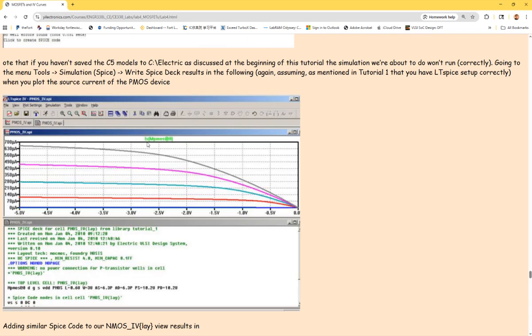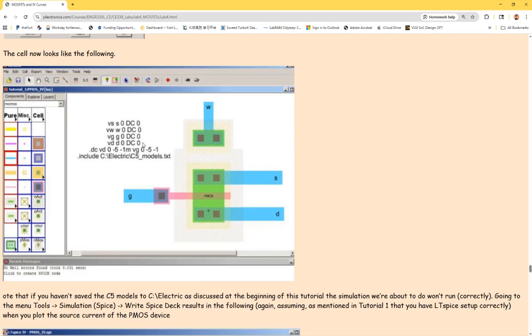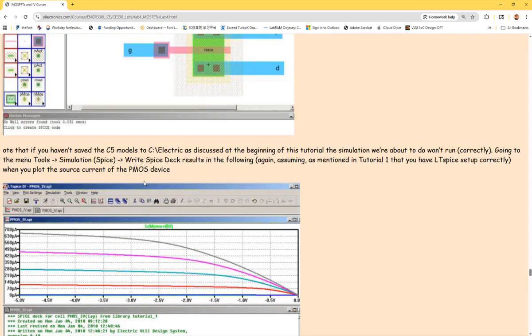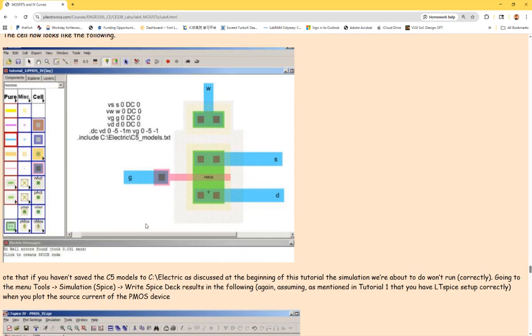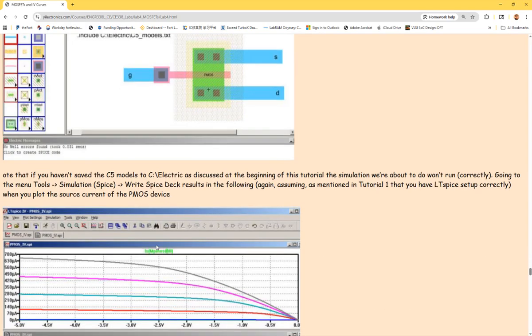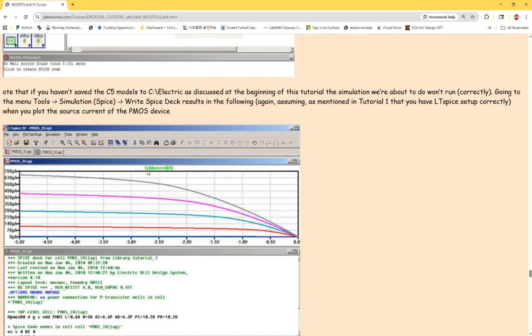And you can see it's IS. It's very interesting with the transistors. You could definitely add a minus sign in front of it to flip it. But for LTspice, there's a default direction of the current. If you plot VS, it shows this. If you plot VD, I think it's measuring the current flowing into S or into D. You know what I mean? So if you're plotting IS,